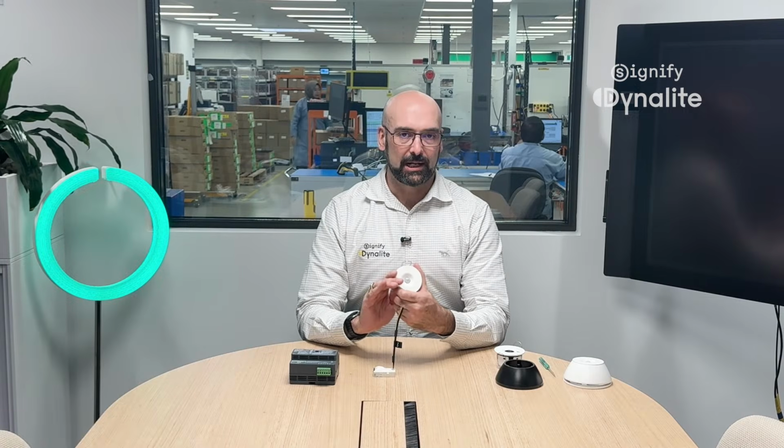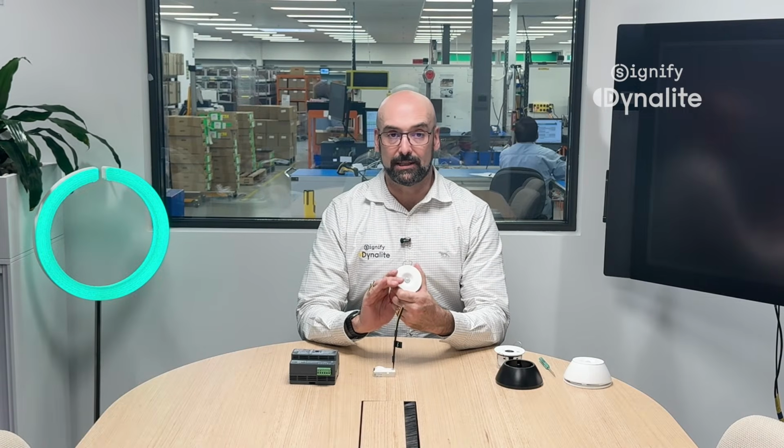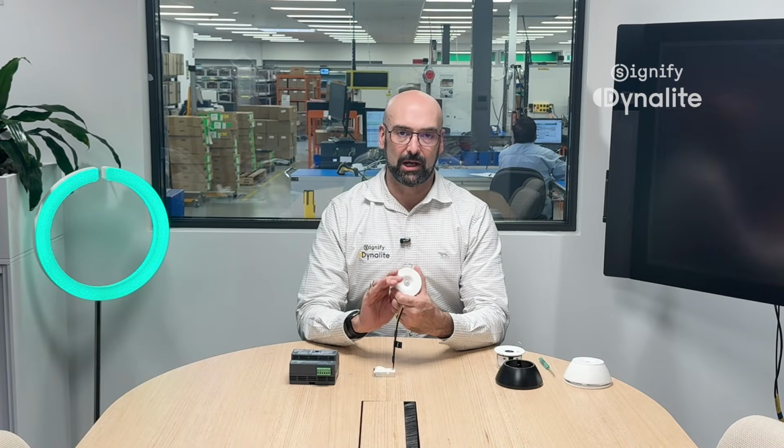The new generation DALI 2 sensors are supporting the DALI Part 303 and 304, which is an industry standard that the projects are specifying and looking for. With our new dry contact input device, this is supporting DALI 302. So again, this is all falling within industry standards, allowing us to be able to claim that certification, but also meeting the expectations from the project that this is a full multi-master system.